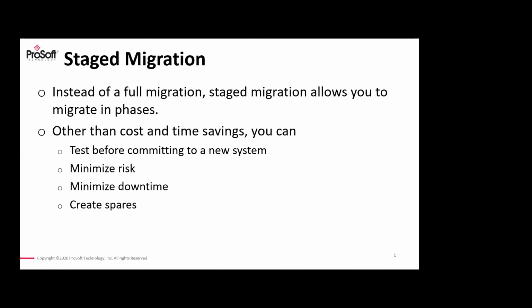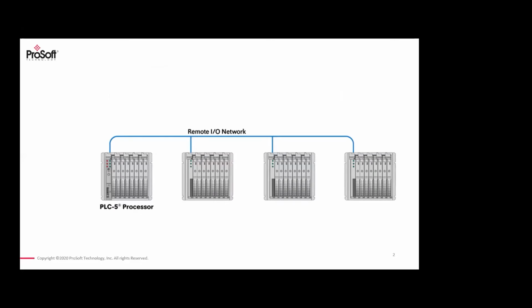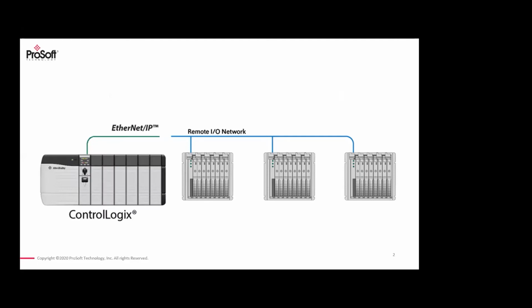For a time, though, you need to have a hybrid system that has a mixture of modern and legacy equipment, which speaks the legacy language and the modern language at the same time. If we go back to our real example, first thing that you can change is your PLC. But your PLC talks Ethernet IP, which is a modern language, while your I/O talks remote I/O.